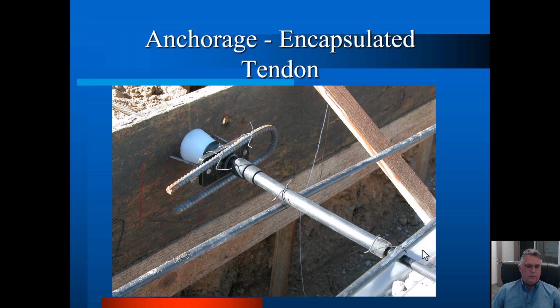And if we were anywhere near the ocean, San Diego, Los Angeles, Hawaii, San Francisco, Newport Beach, Marina del Rey, these have all had black eyes, to be honest with you, in post-tensioning. There were corrosion problems, and the post-tensioners had to fix it. And we understood, and encapsulation came around and was available to us, and a lot of us were using it, and a lot of people weren't using it. They were taking the risk.